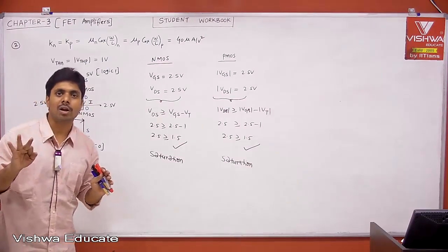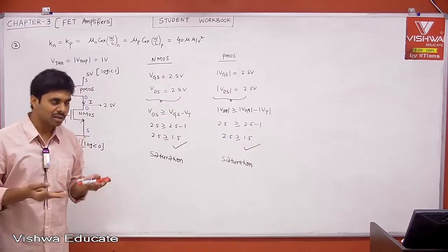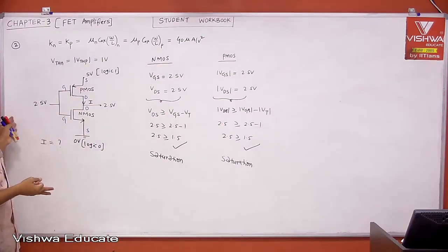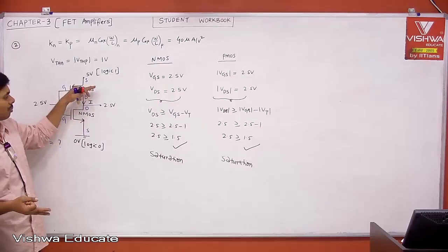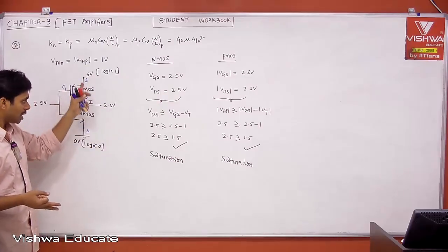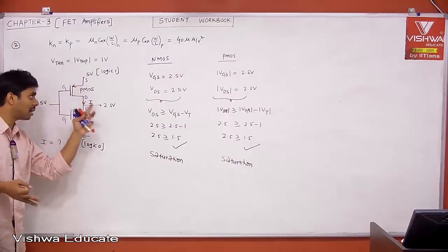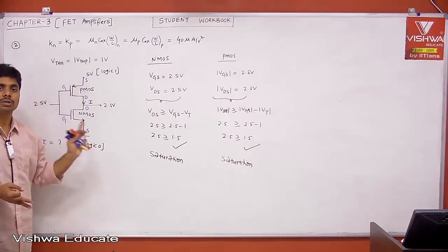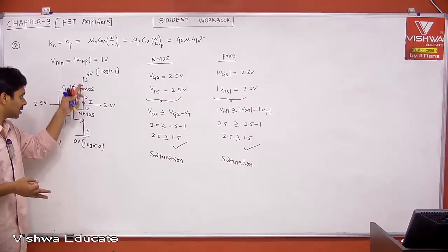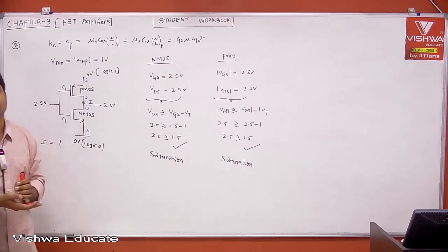And something called switching power. Switching power means, when input is changing from 0 to 1, and output is changing from 1 to 0, not only is the capacitor charging, there is extra power which is going to ground, other than the current which is going to the capacitor to charge. Therefore, this is also one of the extra power components which you are getting.